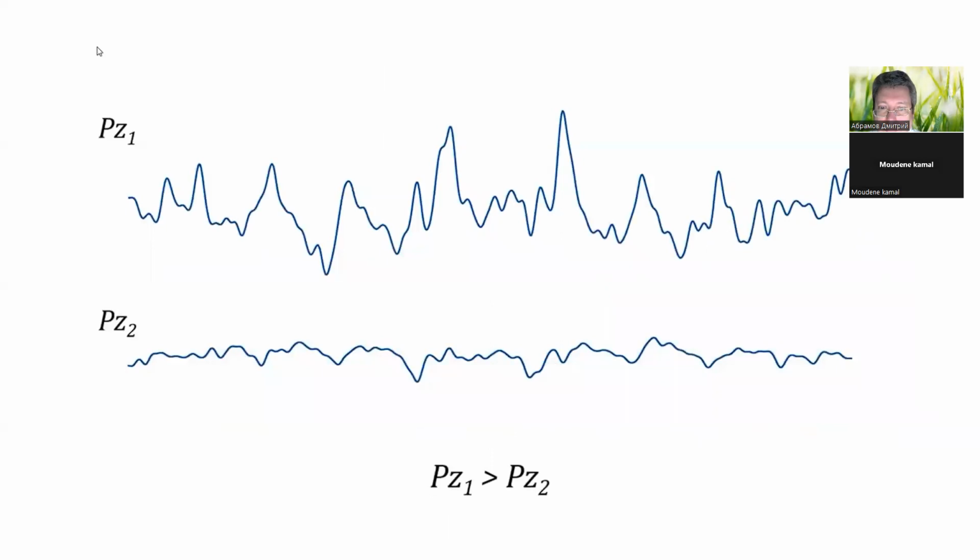The Pz parameter makes it possible to discriminate two surfaces by comparing their maximum heights. Here, we can say that the above profile is rougher than the profile below by just comparing their respective Pz values. But these values do not tell anything about the texture morphology of the surface. How are heights spread between the min and max values? That we don't know.